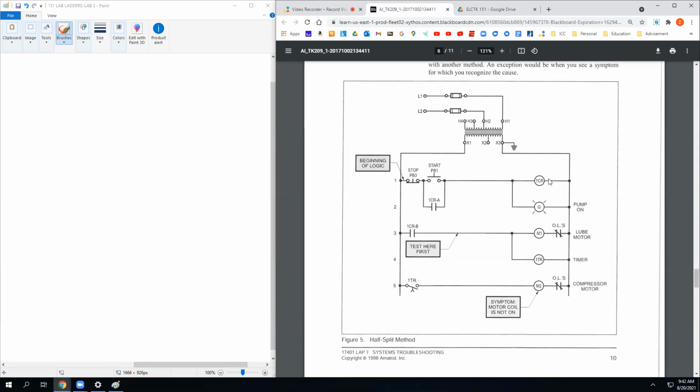You know, this CR1 might energize rung 86's contact, and then a timing relay in series with that might energize another relay coil that's back on rung 3. So if your system is sequential, like, okay, rungs 1 and 2 have to be turned on before rungs 3 and 4 are, and rungs 3 and 4 need to be energized before rung 5 is, then you could do that.